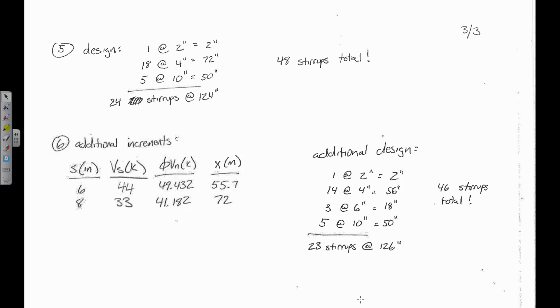So essentially, here's the beam, and the support starts here. So that's x equals 0. The problem states that we have to start out with S equals 4. So the way that we do that is we place that first one halfway over, and then we have S equals 4. Because the idea is that if we had one back here, then that 4-inch spacing goes past the support. That's why. So, does that make sense?